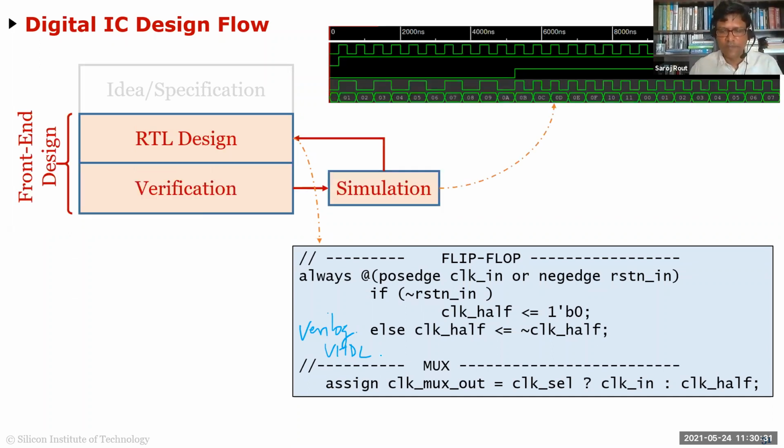And once you have this, you're going to simulate it. Here, for example, you have this design of your SPI and you simulate it using any of the simulators. For example, you guys use EDA Playground. In EDA Playground, you can use any of the Verilog simulators like Incisive or the open source tools. This is purely behavioral in nature, and these are what's called event driven simulations. They just understand events of zeros and ones at a particular time step.